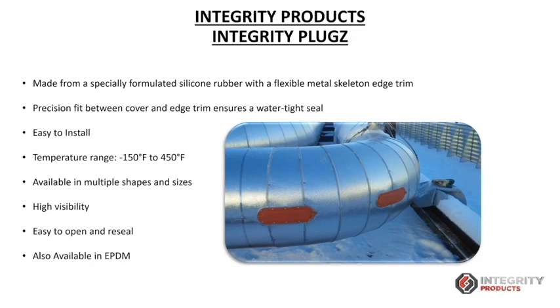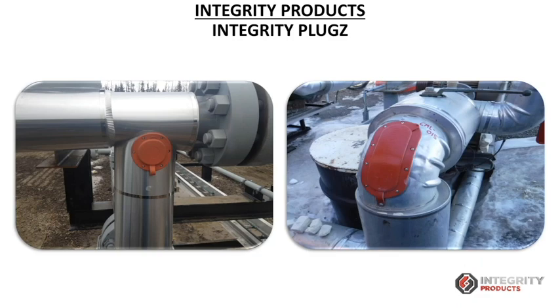Again, I would say it's advantageous over the other commercially available inspection plugs, because it's flexible. It can sit on any profile. Plus, with this packing, we are offering a QR code. We can scan that and get the installation instructions. It also has a template, which allows precise cutting of the metal jacketing, so that any person can easily install it. And here are certain field shots showing our 3/4 round plug and 9.5 inch oval plug, and how they look in real life.